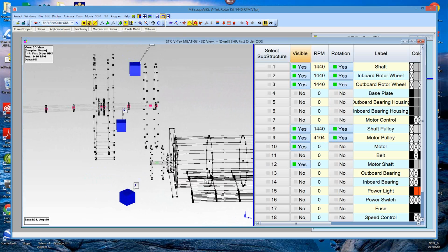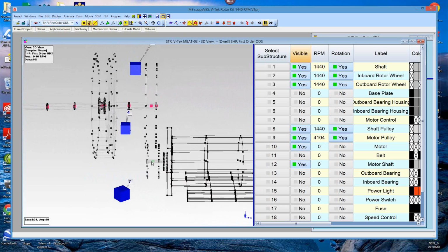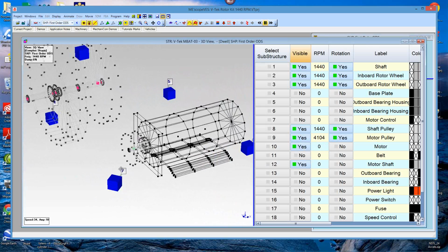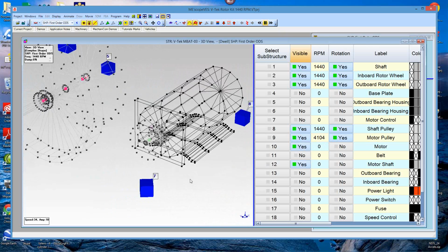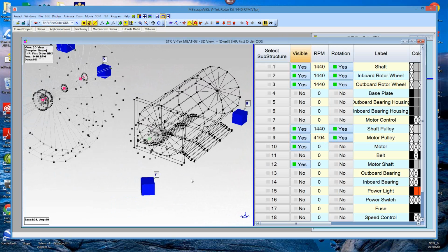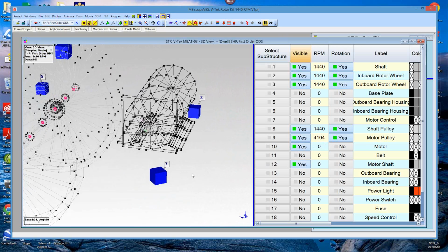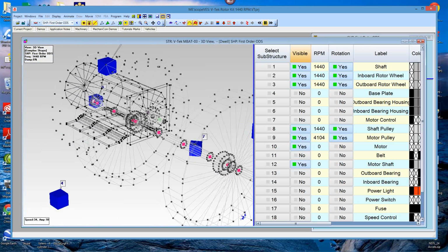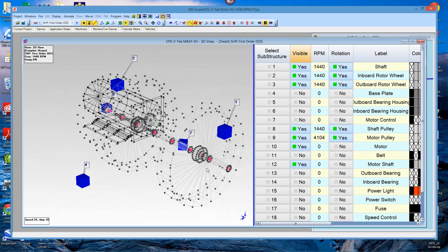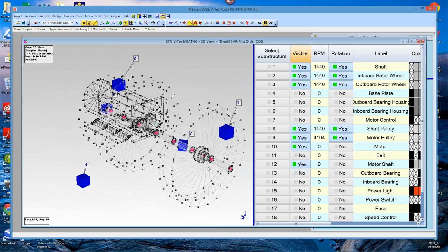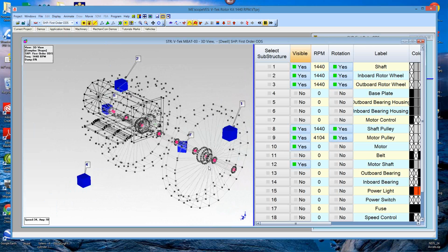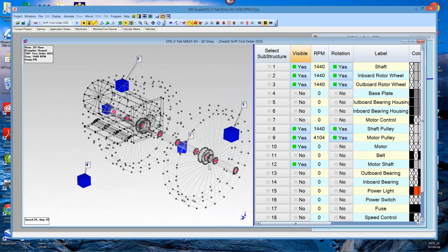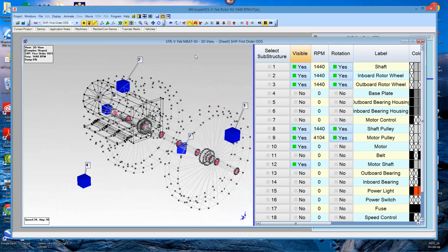You can see it's got a center point there too, that green one, and it's following the motion of the motor. So you have to build it up a step at a time, and then as each point is interpolated, convert its equations to measured, and they will stay fixed as you interpolate other parts of the structure.